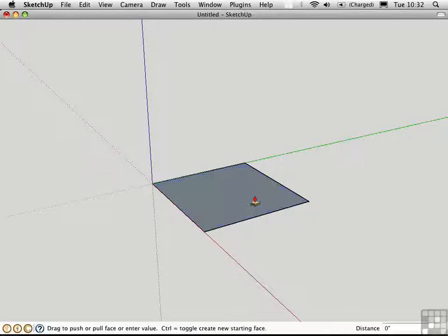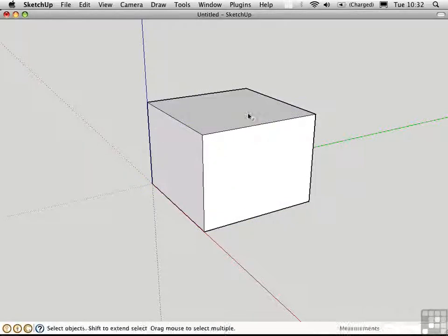We're trying to model the form, which we can scale later. Push-pull this rectangle up, forming a box. Draw an arc on one of the faces from some arbitrary point along the vertical edge to a point that's equidistant from the corner, as indicated by this magenta inference. Make the arc tangent to the edge, and then type in 6s, return, to make an arc that has only 6 segments.